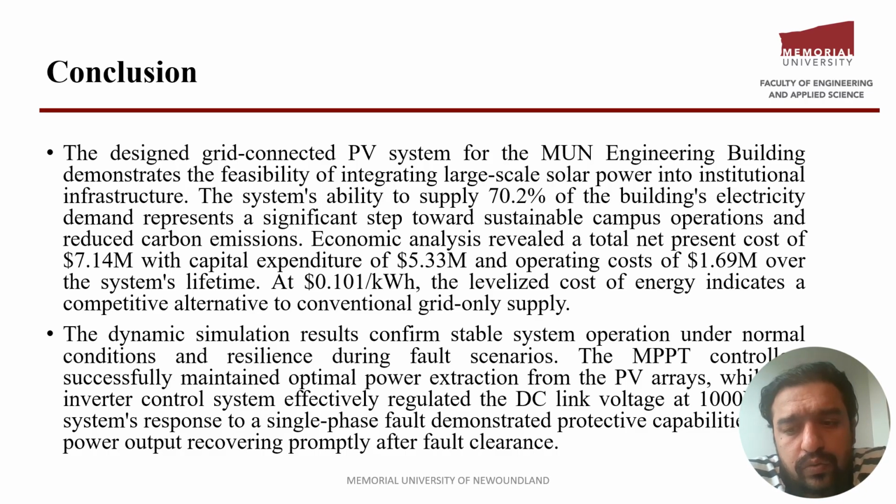We also simulated the dynamic behavior of our project in MATLAB, which we concluded shows stable operation under normal conditions, and resilience during fault scenarios, for example, power recovery after fault clearance. And the last one, the system performance: the MPPT controllers ensure optimal power extraction from PV arrays. The inverter control system maintains the DC link voltage at 1000 volts. This project also demonstrates protective capabilities during a single phase fault.